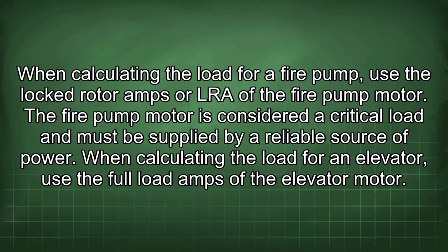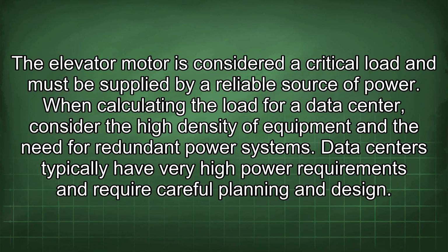When calculating the load for an elevator, use the full load amps of the elevator motor. The elevator motor is considered a critical load and must be supplied by a reliable source of power. When calculating the load for a data center, consider the high density of equipment and the need for redundant power systems. Data centers typically have very high power requirements and require careful planning and design.